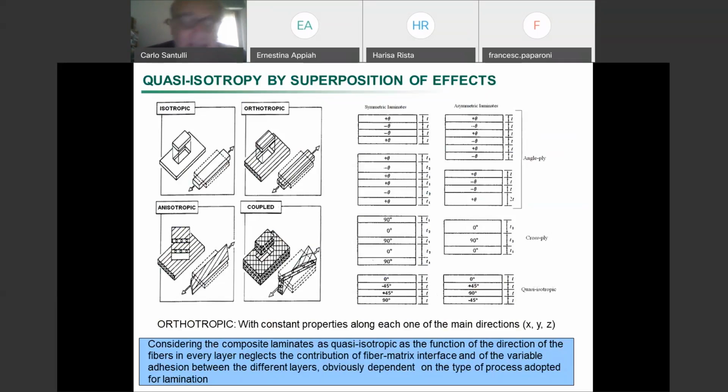Consider that glass fibers are thicker, with a larger diameter than carbon fibers. When I say larger diameter, I mean 25 microns per filament. And in reality, what you find out is that you can lay up a number of layers, and usually you make a number of layers which needs to be a multiple of 4, even better, a power of 4.